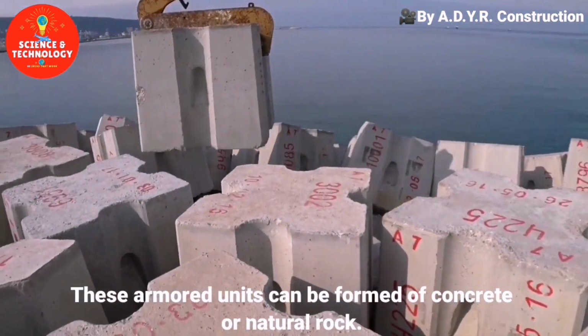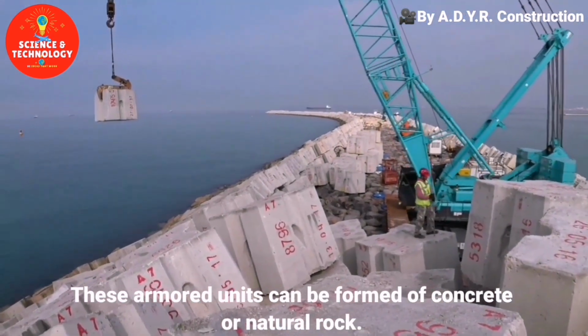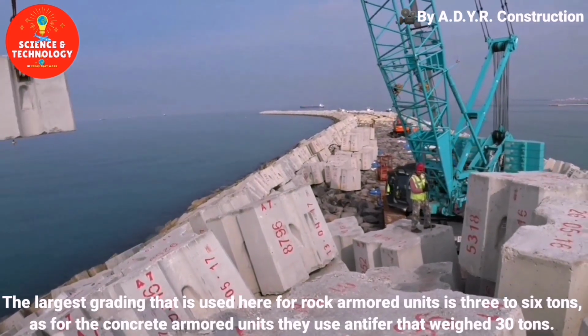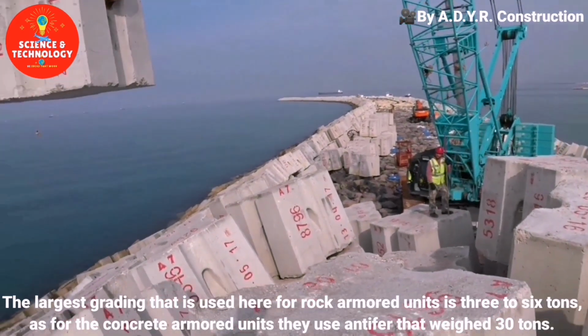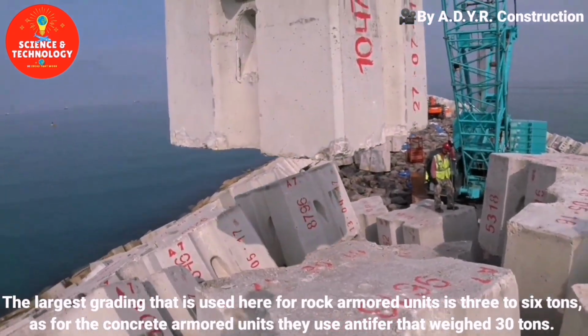These armored units can be formed of concrete or natural rock. The largest grading that is used here for rock armored units is 3 to 6 tons, as for the concrete armored units, they use Antifer that weigh 30 tons.